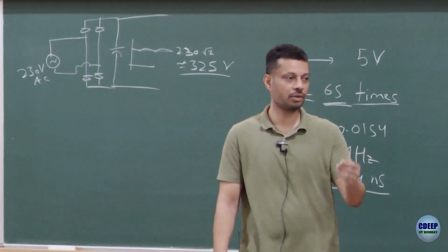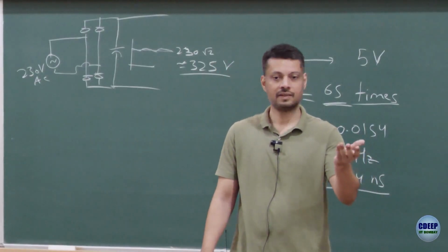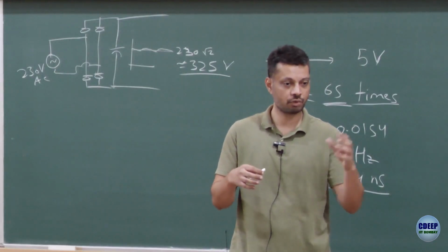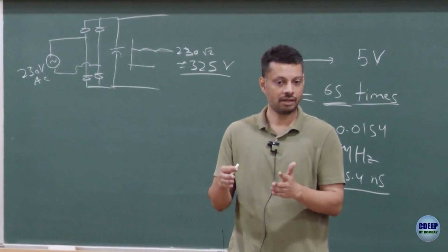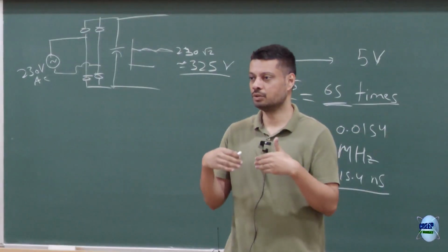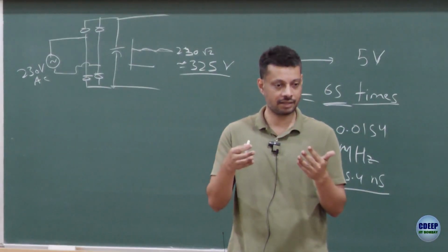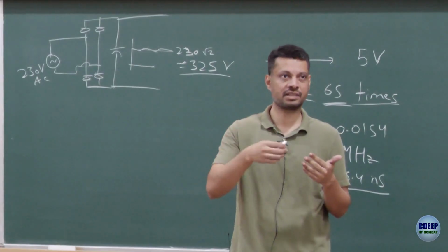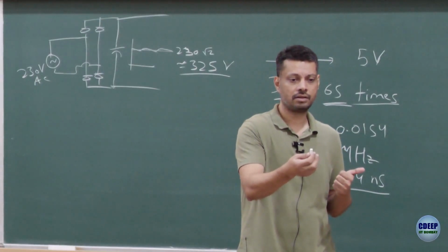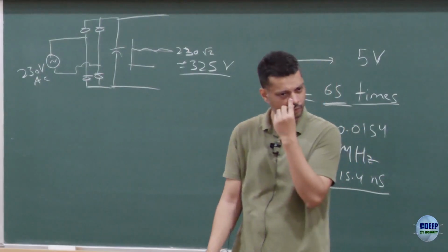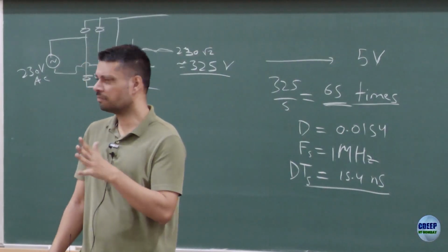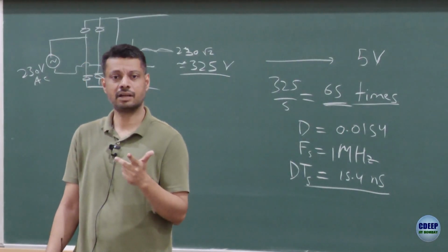If that is your crystal frequency, then inside the microcontroller you would have some kind of a PLL or something which would step down the clock frequency. So assuming that it's 1 to 1, you can execute one micro instruction maybe at every how many microseconds? Roughly one instruction per half microsecond.